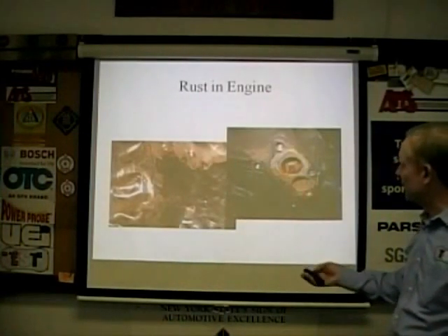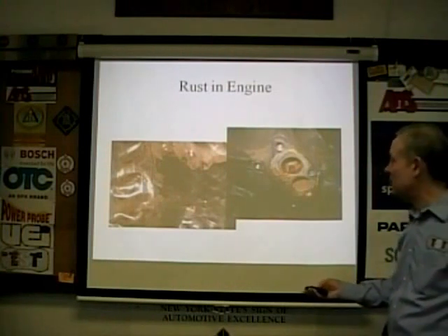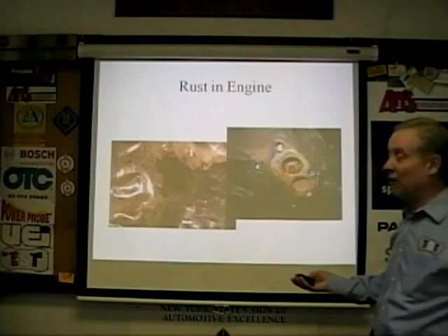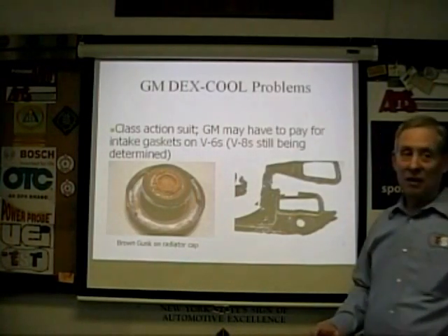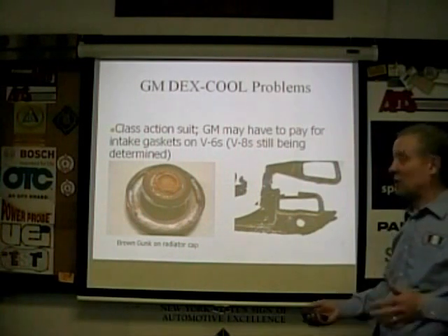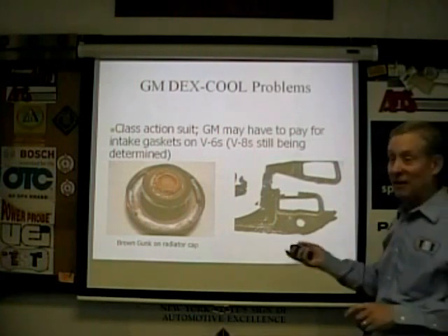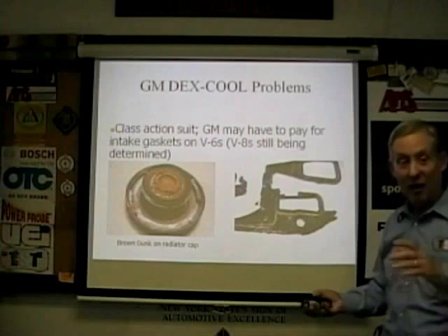Compatibility issue. Rust in the engine, we've all seen this. We don't need to harp on it. Bottom line is, if you see rust in the engine, you know you've got a problem with your coolant. You got to flush very aggressively and then put the right stuff in. And probably check those freeze-out plugs. And oh yeah, look for subsequent damage, not just freeze-out plugs. Plastic impellers on water pumps, maybe an overstressed thermostat, freeze-out plugs, damage to a heater core, any of that stuff.